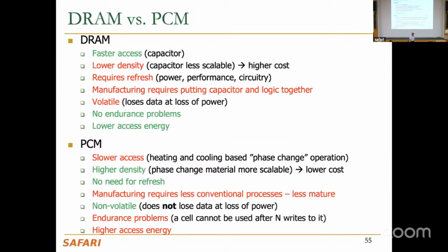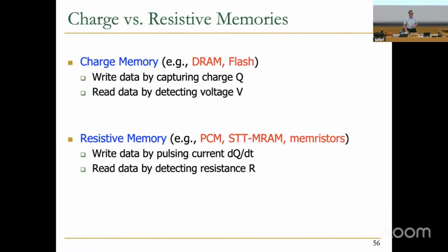So now you all know how DRAM operates in a lot of detail, SRAM operates in some detail, and now at least a high-level overview of PCM. You can see that there are different technologies. I will also distinguish between charge versus resistive memories, especially on the main memory side.